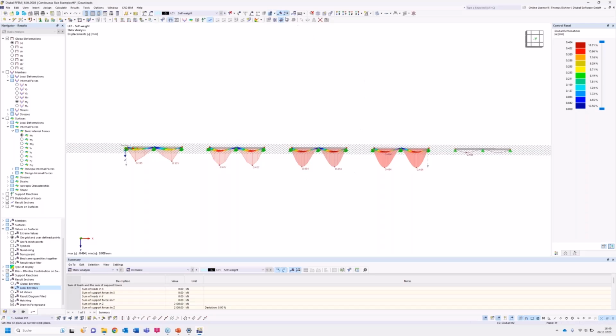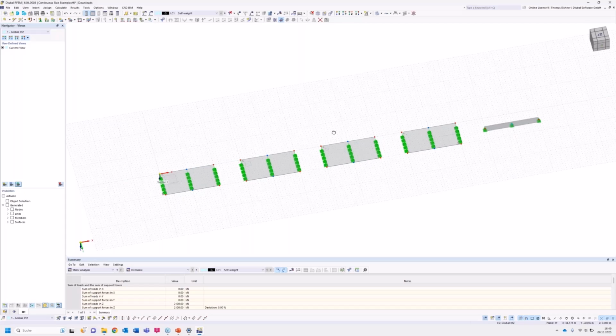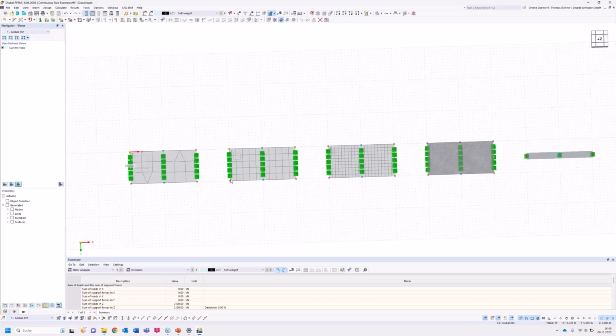And that leads to my rule of thumb, learned in my studies, for the use of mesh size. So I'm going to show the mesh again. We have like 5 elements right here. And here we have quite more, and way more. The rule of thumb I learned was 6 elements per length. So there needs to be 6 elements in the region we want to inspect.